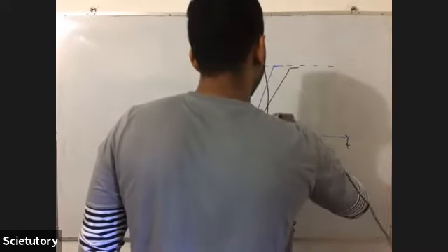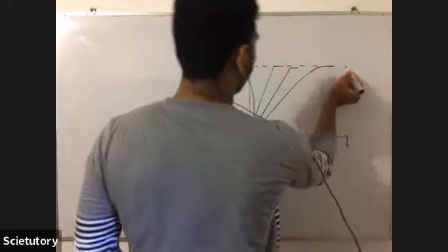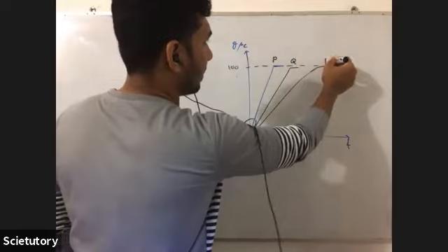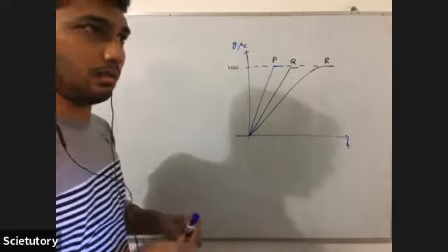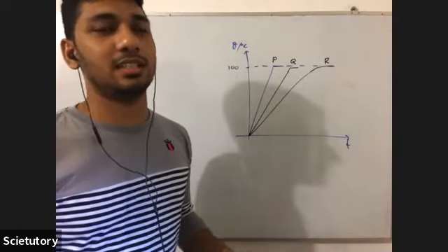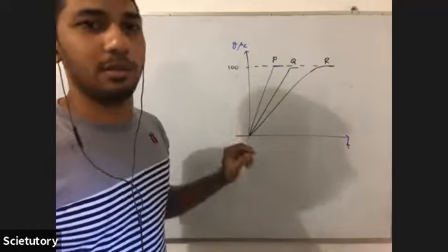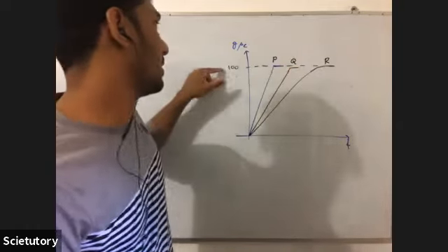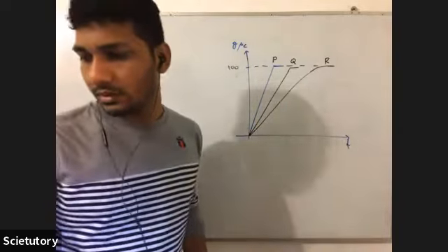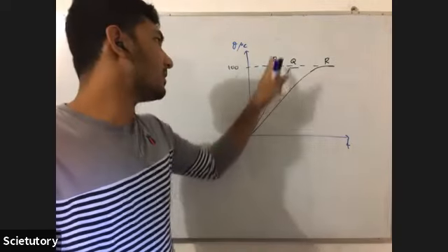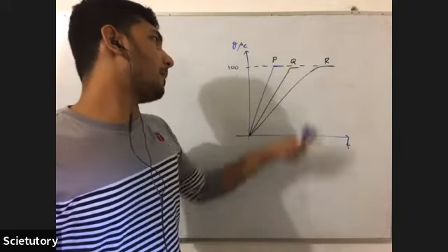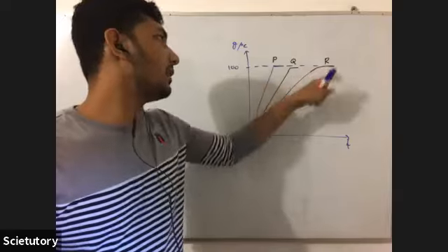So this is with time. Always remember, this is the variation of temperature with time. So which thermometer is quicker? P. P is quicker. Which thermometers are accurate? P and R, not Q, because Q is showing a somewhat reduced temperature, not the exact temperature of that oil. Those are some conclusions that you can take. The fastest is P, and the other two are slower, and Q is not accurate. P and R are accurate.